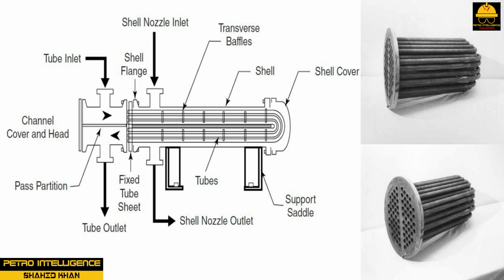U-tube exchangers are specially designed for large temperature differentials. The U-shaped design allows the head to float and accommodate the thermal expansion of the tubes. Each complete U-tube has a single fundamental frequency as flow passes over it. Segmental baffles placed at equal distances provide the support and framework that bond the tubular bundle into a single unit. Longitudinal baffles may be used to direct fluid flow.